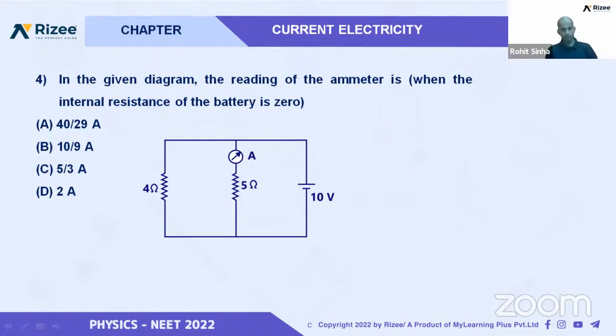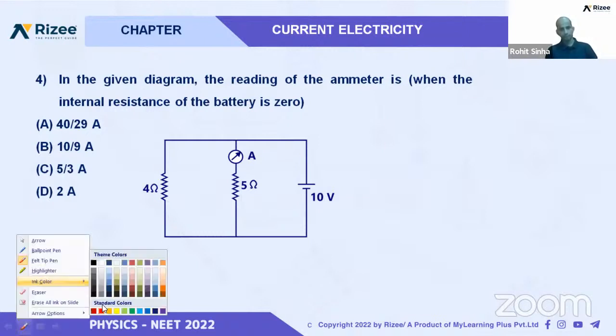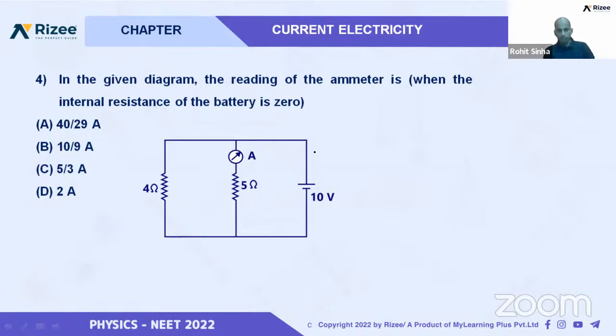Okay, let us see. Nobody. See, you should remember this is a 10 ohm resistance. That means here it will be 10 volt, and here you can say 0 volt. So the potential difference is 10 volt. Here also 10 volt, here also 10 volt, because in between them no resistance is present, so there is no drop of voltage.